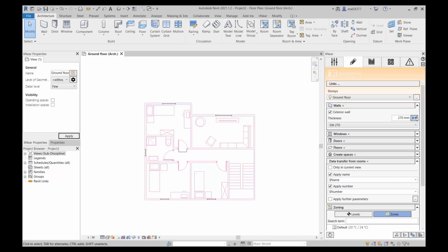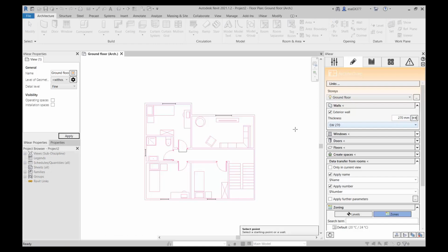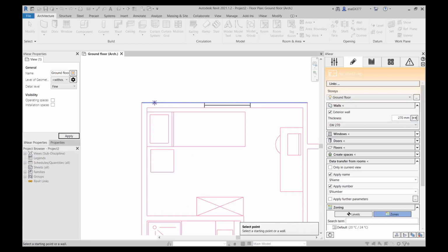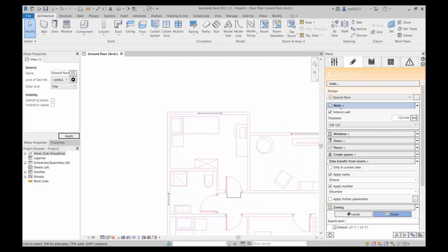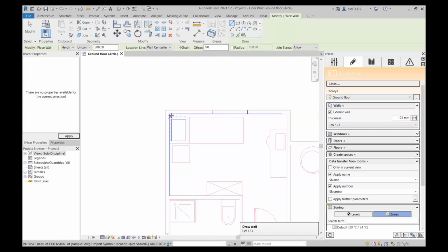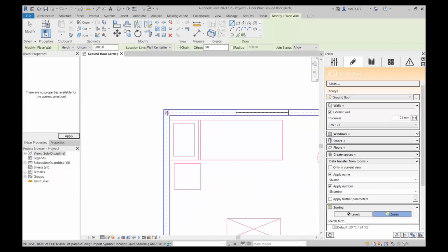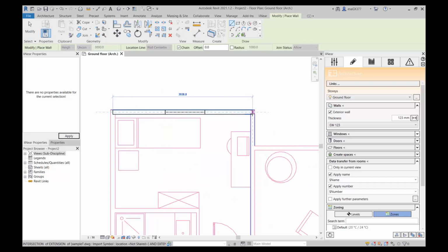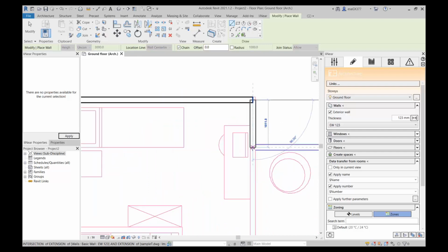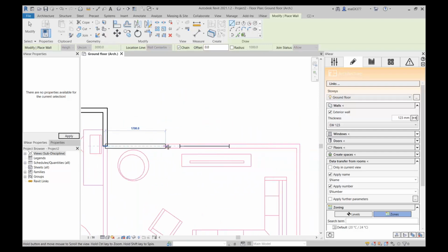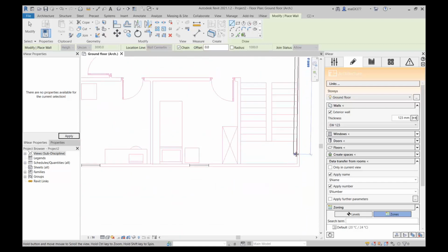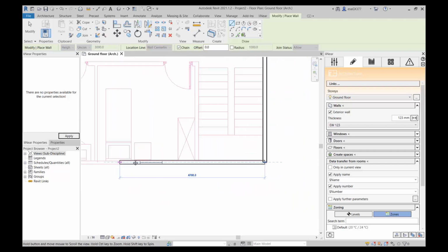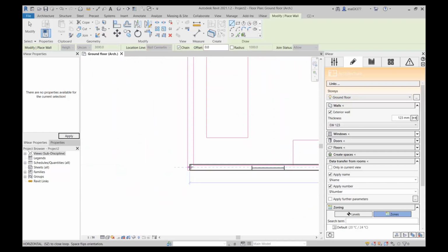And in Construction tab, we have this Walls command. Here, we can activate this command and select the thickness of the wall. And then when you activate the main command and construct these external walls, as you see, you can do this very easily. You just have to select the midpoints and continue to draw around the floor.